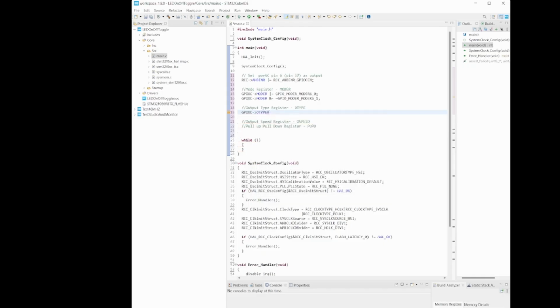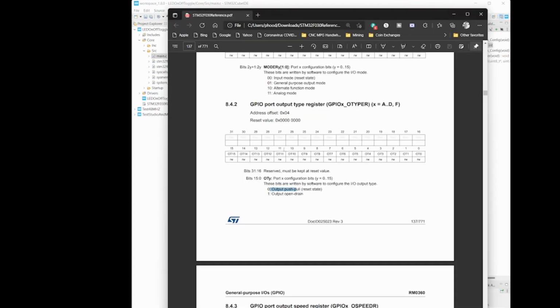And we're going to reset this one, or set it to 0, using the AND NOT bitwise operation. And we're going to use the control space again to go to the one we need. And since this is actually showing you only a single bit, let me show you why that's happening. So you can see that even though this is a 32-bit register, you're only using bits 0 to 15, which is 16 bits. All of these other ones are reserved.